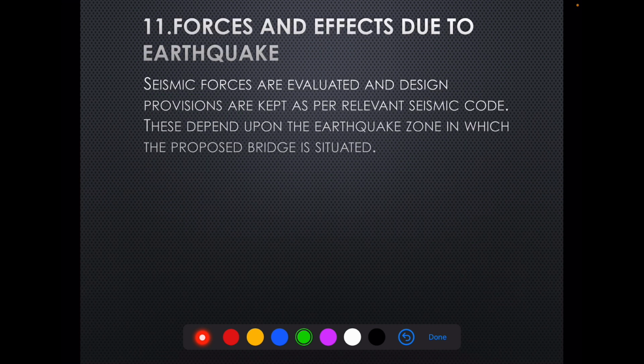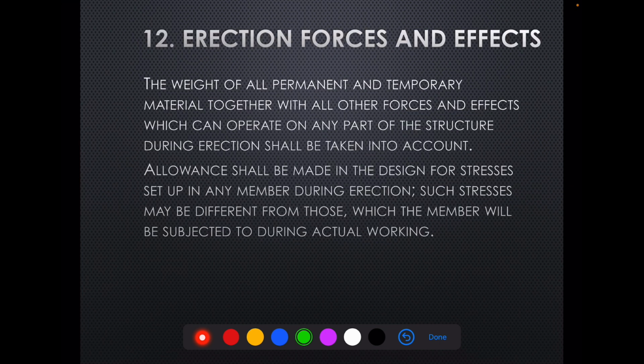Then forces and effects due to earthquake. Seismic forces are evaluated and design provisions are kept as per relevant seismic code. These depend upon the earthquake zone in which the proposed bridge is situated. Erection forces and effects.